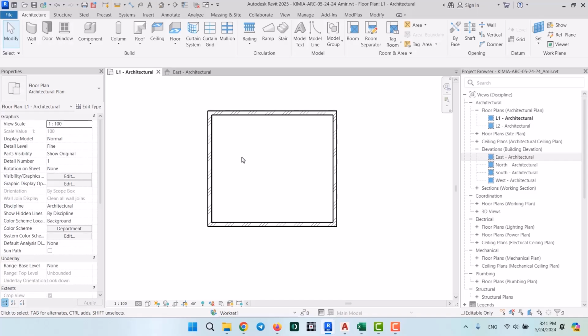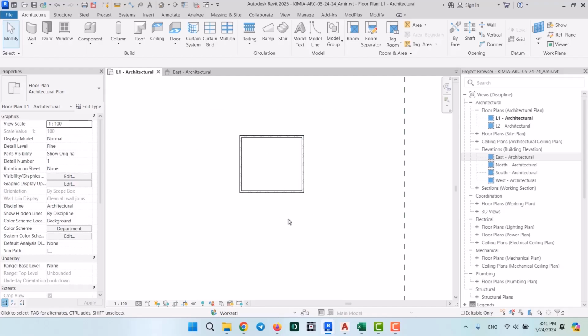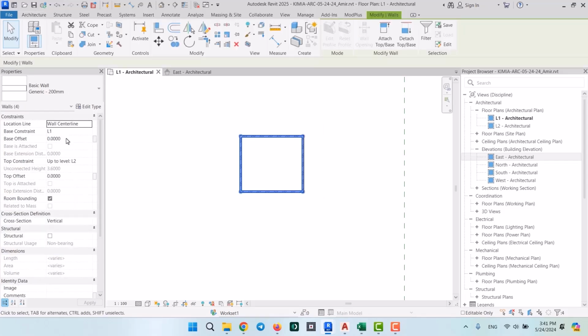For example, let's say that it is 3, but then changes to 2.80. Okay, so what should you do in that case? The offset is already required to change. After that, you would have to select all of the structural base walls that you've drawn, and then go to their base offset value, which you can find the parameter here, and then change the value by however amount that it is needed. That actually isn't a very ideal thing to do, and you should never really do that on your projects, especially when you're working on the bigger ones, because like I said, it's not technically right to do.